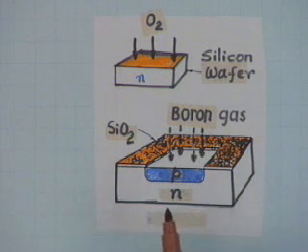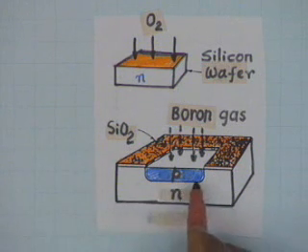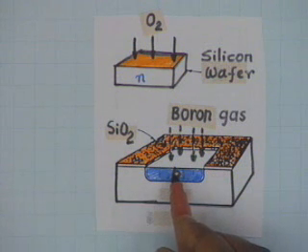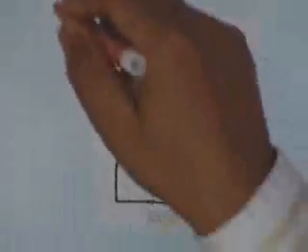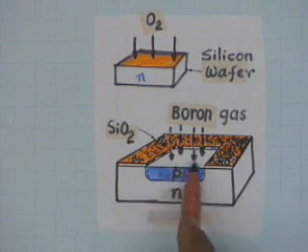These things can be very precisely controlled, and therefore what you have made now is a p-n junction. A p-type material metallurgically diffused into an n-type material, and therefore a junction is created, and this is what is a diode. All that you have to do now to make an electrical device is to deposit a metal.